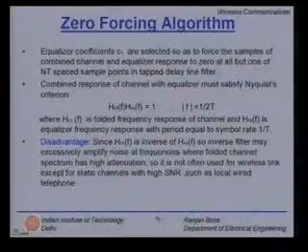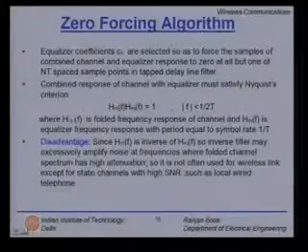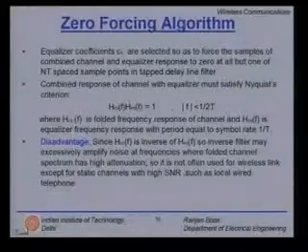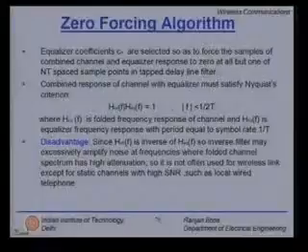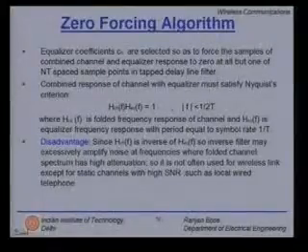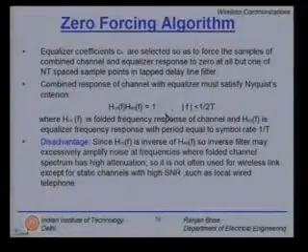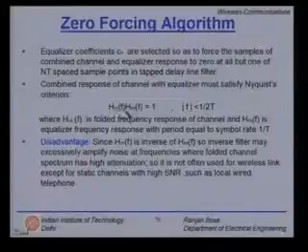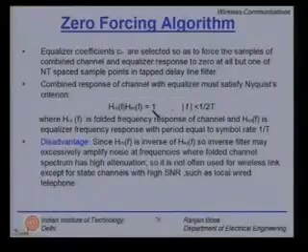It means it is trying to simulate the Nyquist condition, wherein other than its own sampling instant, for all other instants it is forcing the value of the symbols to be 0. So here is the combined impulse response: as expected for any adaptive equalizer, H_channel(f) times H_equalizer(f) is equal to 1.